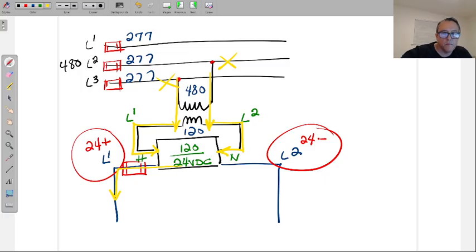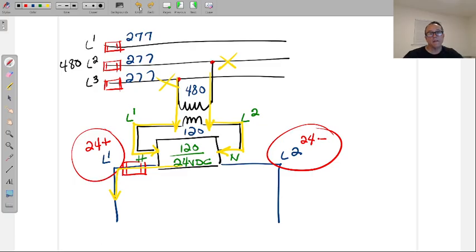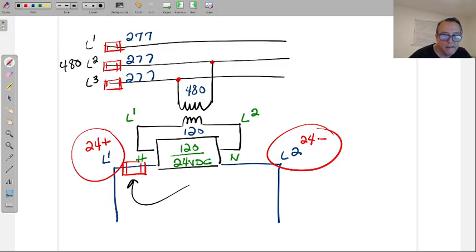All right, now in this module, we don't have PLCs, but here is where the PLC side would be. It would be over here. So now I got this very expensive computer getting power from the 24 volt DC power supply that's about to get fried. So I can have a short circuit on that power side, fry thousands of dollars worth of equipment, where a simple little cheap, roughly, let's say $5–10 fuse saves all of those thousands from damage.